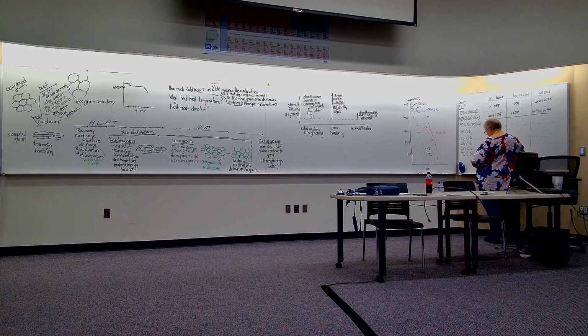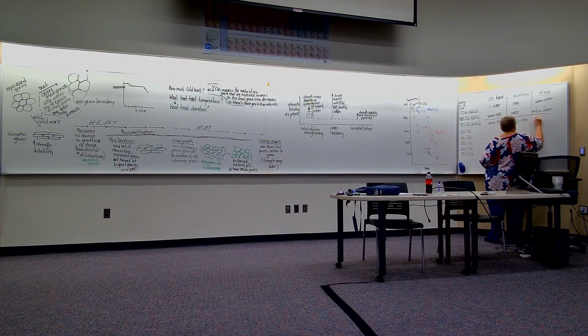And the 50/50 was all liquid above 1320, both phases 1260 to 1320, and below 1260 is solid.